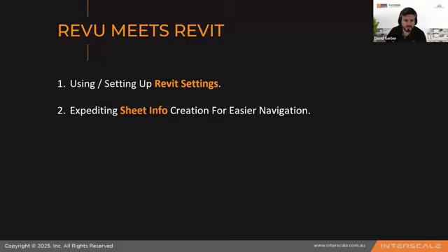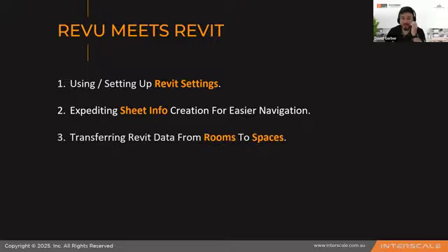So I'll show you a couple of examples. All the sheet labels, sizing and everything, and even the viewports will come out of Revit if you have it. And if you're not using rooms, definitely use them, because that room information will bring in areas and spaces. So then you can even tag, like, there are 5 lights in room 1, for example.